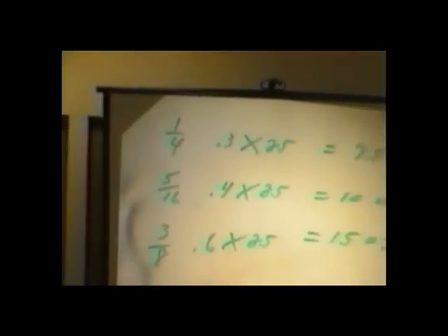Yes. So the units that we have, different line sets that are considered standard, already include that many ounces. Just for an example, because I want to be able to draw this up here so you can understand it. You know, it's one thing to be able to understand it, but it's another thing to be able to draw it so you can understand it. We're going to use an example of a data tag, and let's just say it's a 3-ton. The data tag says that it contains R22 and it contains 51.7 ounces of refrigerant. Only as an example.